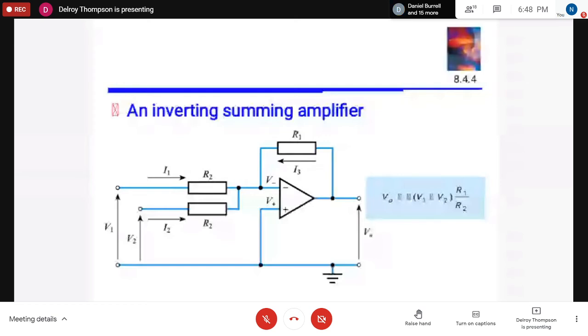So your output voltage would be? So I'm going to give a general equation first, so it'd be minus RF times IT, and then IT would be broken down. It'd be V1 over R1 plus the independent current from each source. So V1 over R1 plus, forget V2 about the current now, because the currents are being expressed in voltage and resistor. Yes, sir. So V1 over R1 plus V2 over R2, sir. Okay. So what we're saying is that this network, called a summing amplifier, you can see that the output voltage is a sum of the individual input voltages. Are you seeing that?